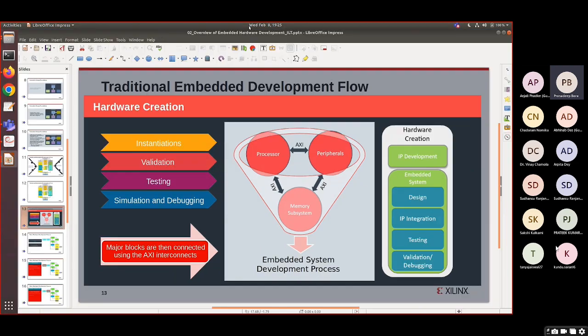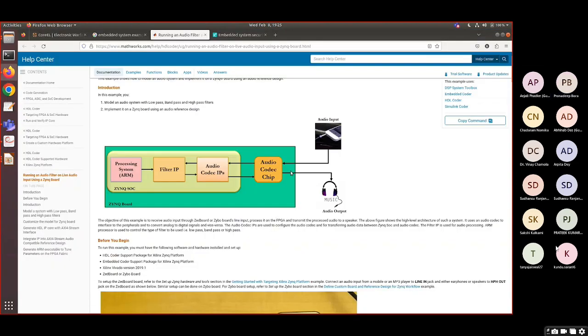So what I mean to say is, all the information that will be passing throughout inside the chip should be of AXI interface, because the ARM processor can understand data only when it is sent through an AXI standard. We'll discuss more about the AXI standard, but this is the de facto standard through which we'll be sending data to and fro of the ARM processor.